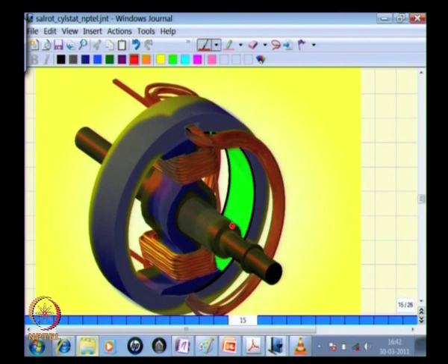And what we have obtained is the flux density distribution as we travel around the circumference. Note that the axial length of the machine is not included in that expression, which means essentially we are assuming that this flux density distribution is constant along the axis of the machine. Along this axis in the stator, whatever value of flux density you encounter at one point, it is the same as you travel along the axis, but around the circumference we have determined what the distribution is.